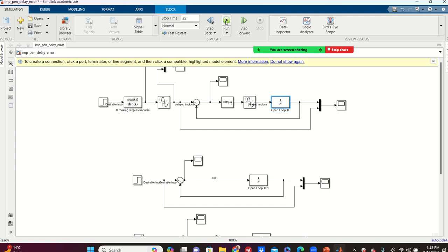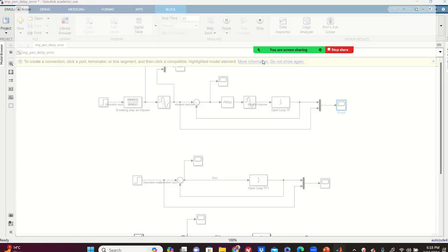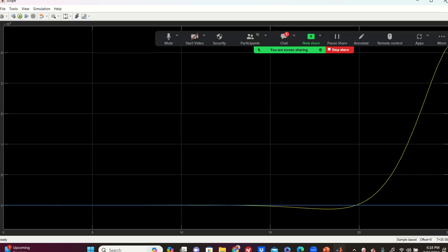Okay, so if I run this, see that huge divergence going up to 10 to the power of 4? Exactly the visualization of this is when the robot failed: it picked up the item but couldn't go over the offset and put it on the green destination. So if you want to fix it, you have to design a delay compensator or predictor. See what I'm saying, everybody?